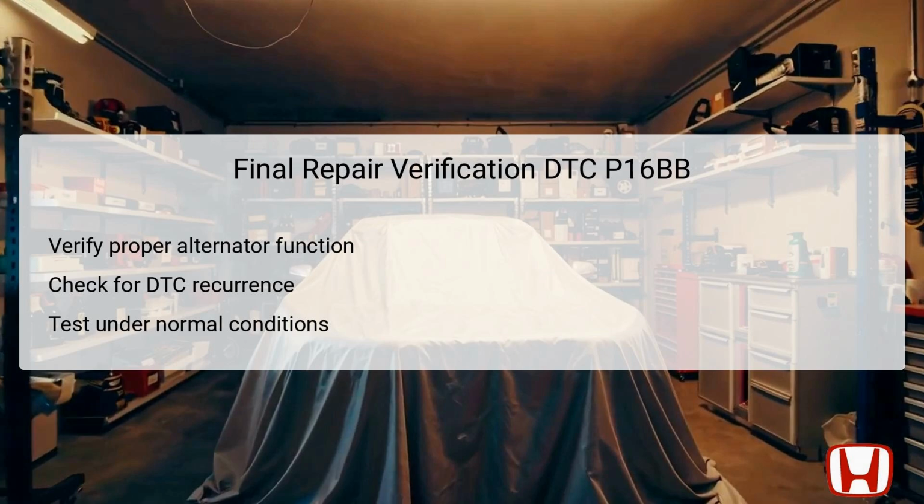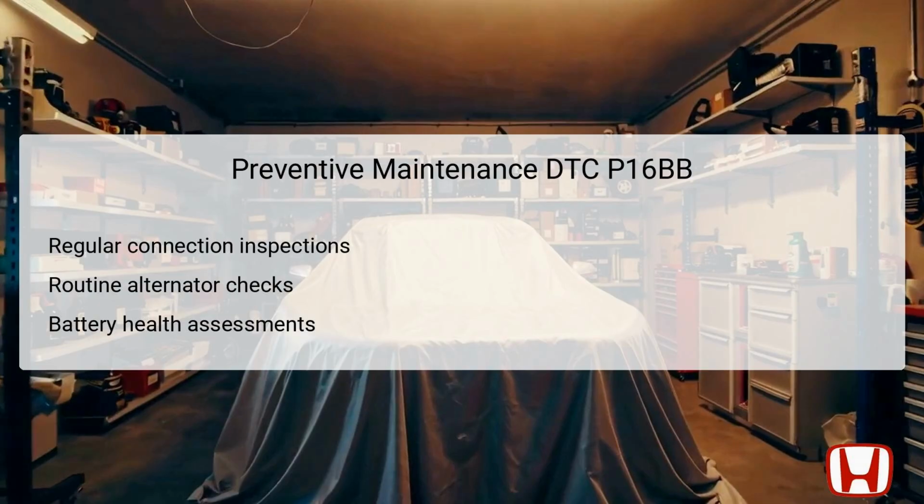Preventive maintenance is crucial in maintaining the functionality of the vehicle's electrical systems and avoiding future occurrences of DTC P16BB. Regular inspections of electrical connections, particularly at the alternator and fuse relay box, can help detect potential issues before they escalate into major problems.